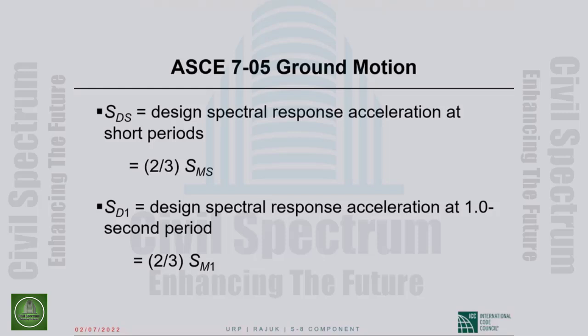ASCE 7 does not really define a design earthquake except by saying that it is 2/3 of the maximum considered earthquake. Okay. The maximum considered earthquake is defined, and I will go there soon.